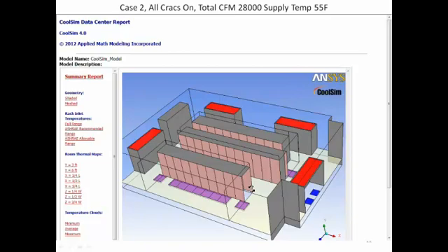The best thing for any piece of machinery is to run it within its design specifications. Run it where they designed it to be run. We always used to call this running off design center. If you run off the design center of any piece of equipment, you don't know what's going to happen. They didn't design it for that. So it'll fail. The design point. Yes.